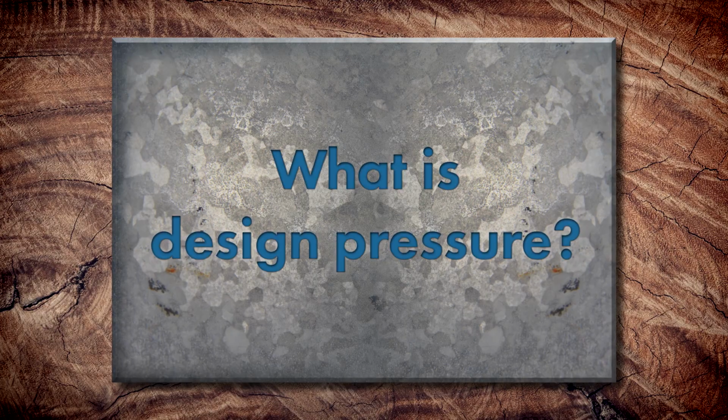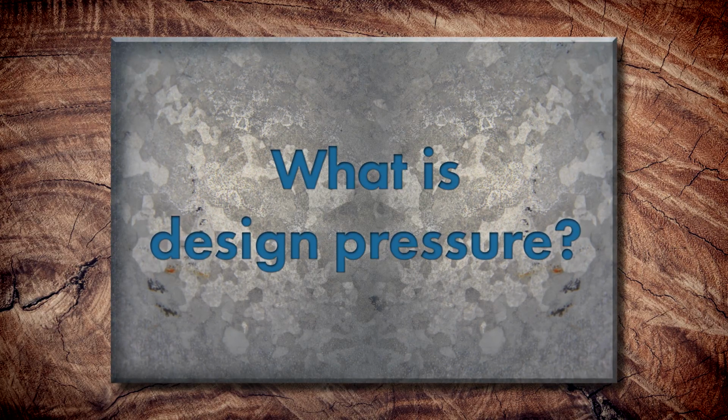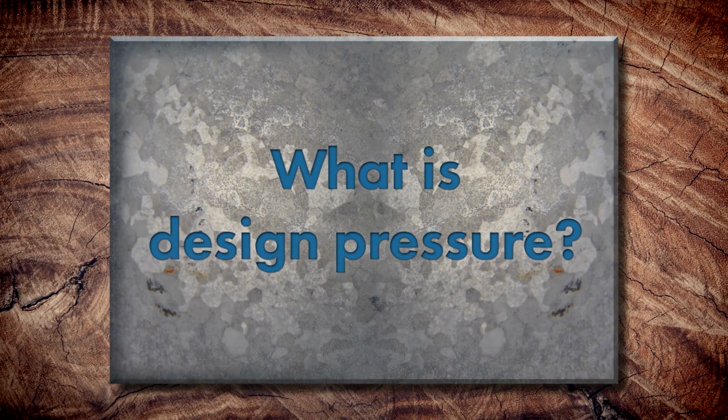Can you tell me what design pressure means, first of all, just in general? Okay. So when you do an uplift test, whether it's a UL 580 uplift test or a 1897 uplift test, those are both over solid substrates, or an ASTM E1592 test for over open framing, you get two numbers at the completion of your test: a test pressure and a design pressure.